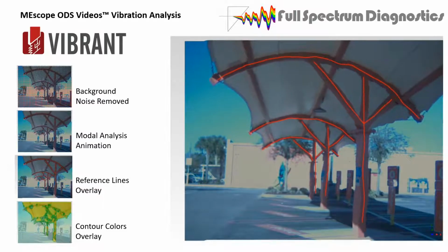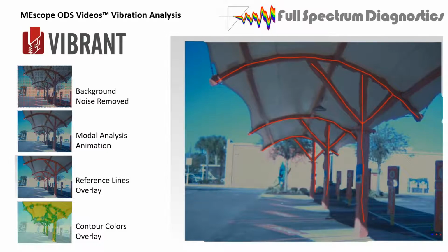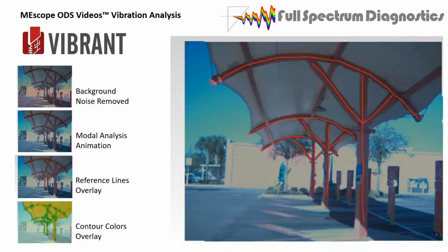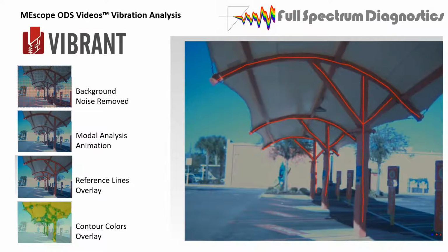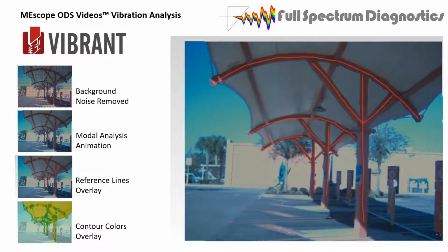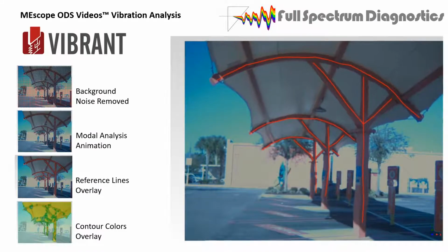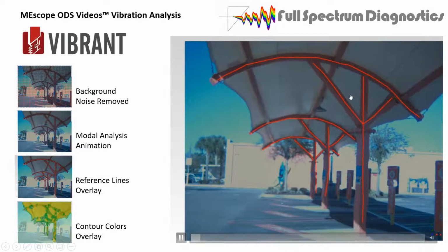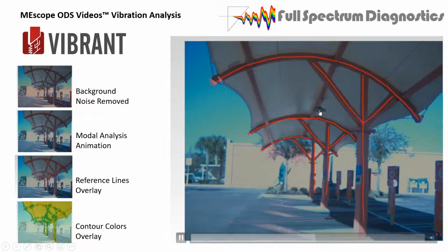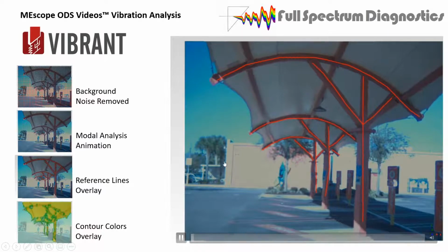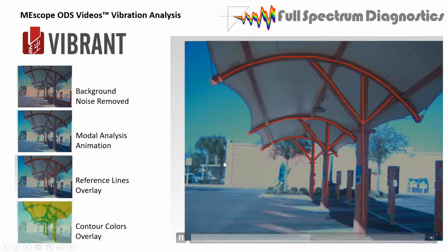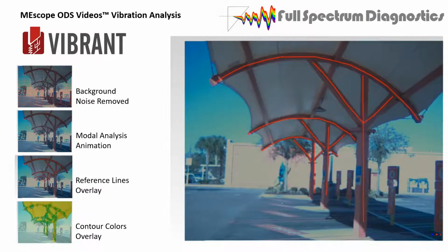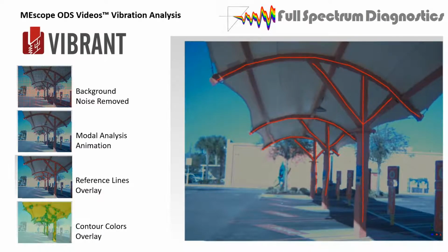And there's a couple of different options in the software. You can normalize the response, especially for modal analysis. If you're sitting right on a natural frequency, it should be normalized. If not, and you're looking for motion like this that's a little out of phase and a little more realistic, you can take the normalization off and look at the mode in a complex view. So whatever you recorded it in will show you how it looks.